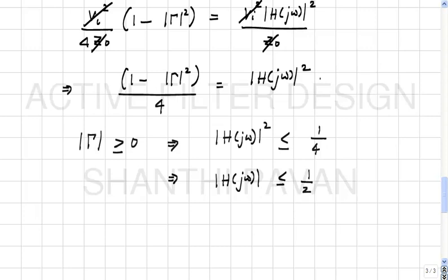So if we are satisfied with the DC gain of half, then everywhere in the passband, the magnitude response is close to the value at DC in some sense. In the Chebyshev case, there is some small amount of ripple. In the Butterworth case, it is kind of maximally flat, and same with the inverse Chebyshev and so on. So one thing we can conclude is that in the passband, mod gamma is a small number.